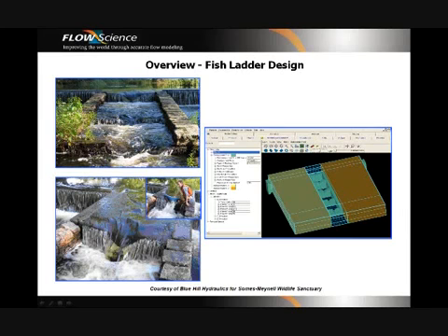The lateral variation of the velocities in fish ladders contributes to the goal of enabling fish to climb them. The alewife fish swim at about 3 feet per second and are able to sense lower velocity zones. For a successful fish ladder, a key requirement involves the creation of contiguous pathways where water velocities do not exceed speed limits.